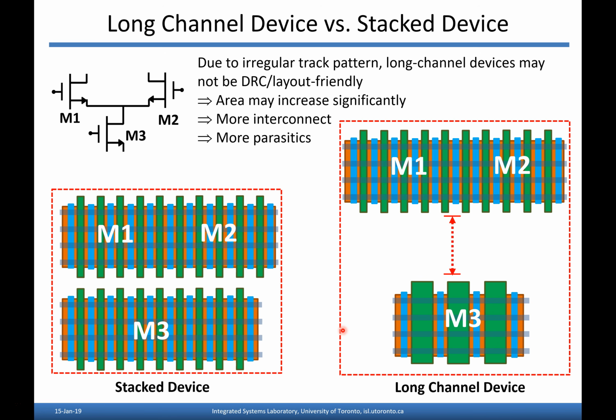You can literally insert these things in the layout called cut lines that just define a break between one transistor and the next. And that lets everything just shrink right down. So that's usually the style. In summary, you can have longer channel devices, but unfortunately, they have to be kind of separated and off on their own.